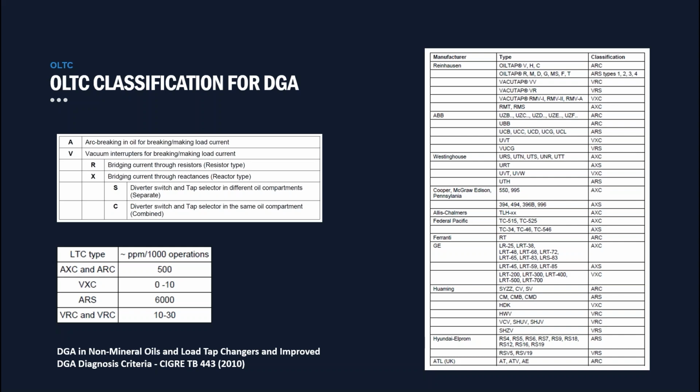If you see heating in a transformer, look at the recent electrical test results. If the levels continue to go up at a high rate, you need to think about taking the transformer offline and doing electrical testing. You can also do thermography to look for problems like overheating of the tank, and particle count testing. But do the corrosive sulfur test if you see elevated levels of methane, ethane, and ethylene.